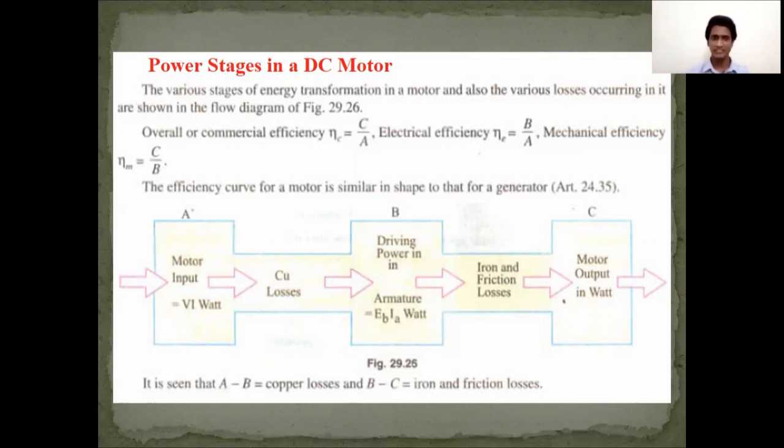Similarly, in a DC motor, we give a supply to my field winding to produce a magnetic field, and we give DC supply to my armature windings also, so that current carrying armature conductors are placed in a magnetic field. Then it experiences a force called the Lorentz force, or a torque, and it starts rotating. And that is the basic working principle of a DC motor.